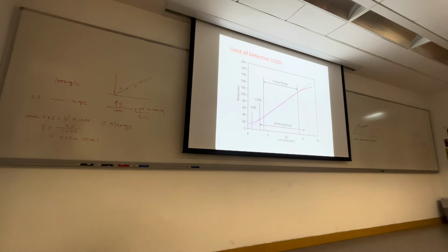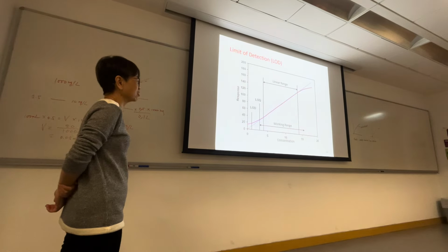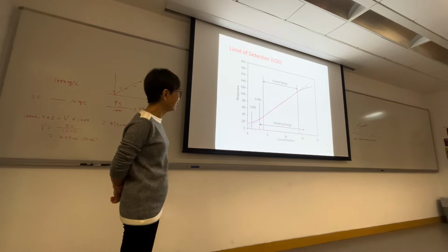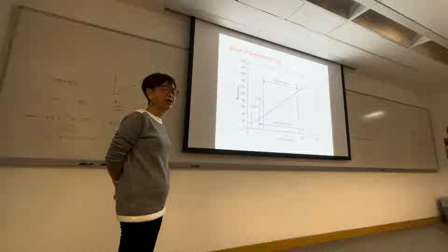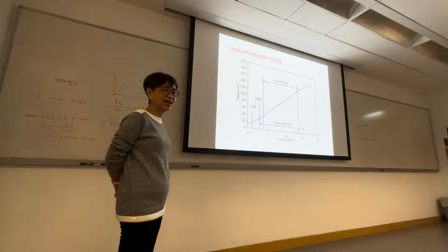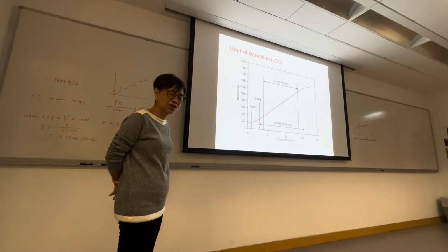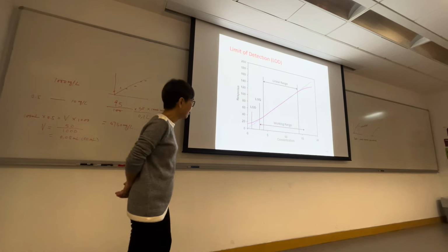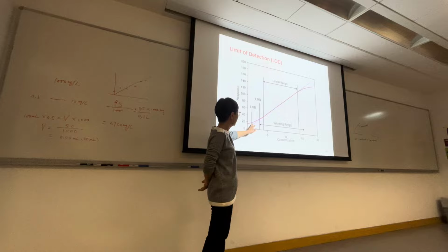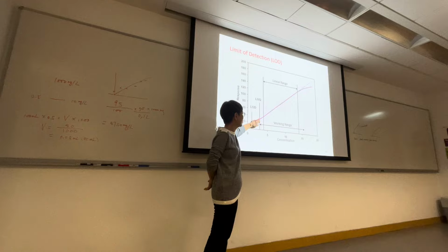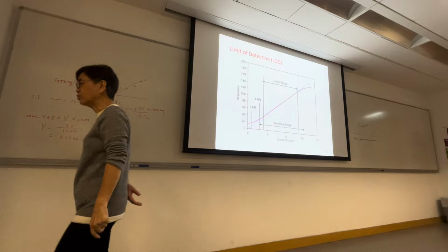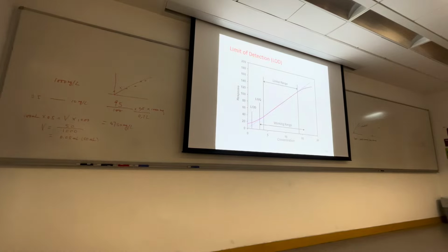That means we target the linear range for quantification. But below the linear range, you always have a high possibility that the quantified level is uncertain. So at the lower concentration, the signal will be much lower. Then this is the LOD. At a higher concentration, the signal is higher. Then we define it as the LOQ. But how to establish this LOD and LOQ?